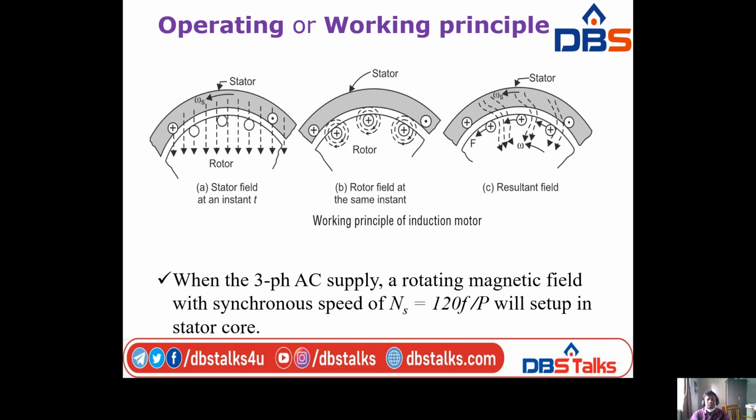Next concept is the working principle of the three-phase induction motor. The three-phase induction motor mainly works on the principle of induction. Whenever a three-phase AC supply is given to the stator, a rotating magnetic field is produced in the stator.